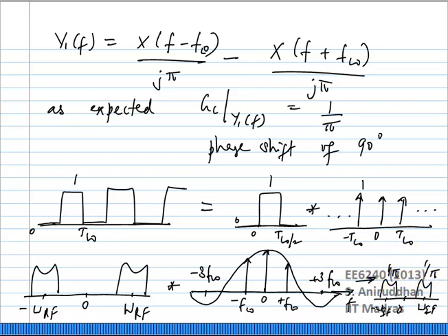So now we have found the gain of the first portion. We need to find the gain of the second portion and then add the two together to get the overall gain. But it should already be clear that the sampling mixer potentially has more gain than the return to zero mixer, because even one part of it has the same gain as the return to zero mixer.